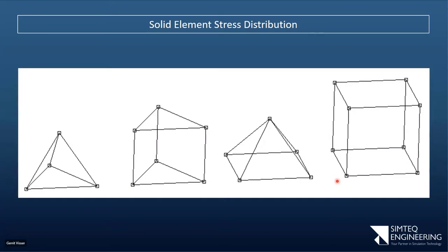So that's the limit. Okay, so if I look at the stress state of this element, it says every one of these faces can have a constant stress in every one of the directions. Said another way, the whole element can only have a single stress in the X, in the Y, and in the Z direction. If I look at this element, try to align your brain so that this is the bottom face and that the top face.